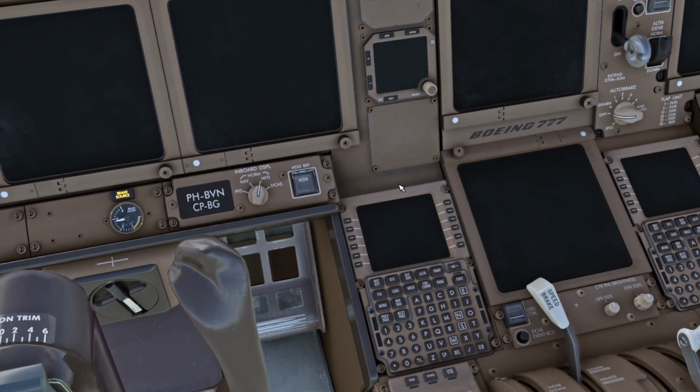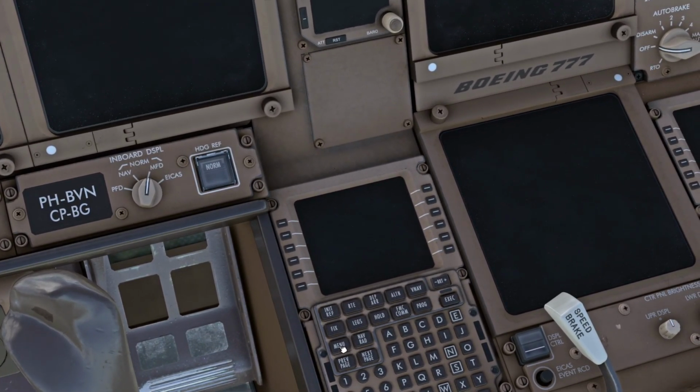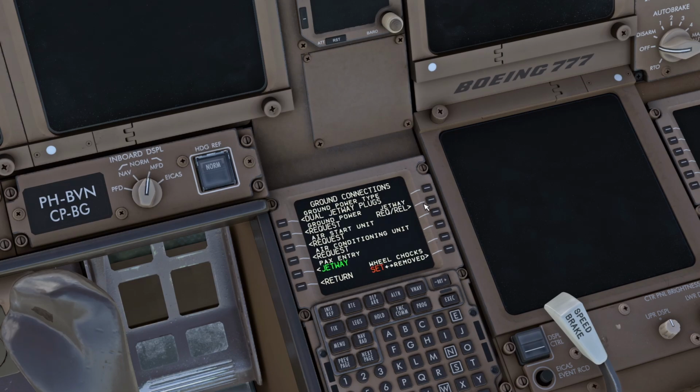For this we need to hook up some electrical power on the airplane. We do this in the PMDG 777 by holding the menu button in this cold and dark state. It will make the CDU come alive so we can access the FS Actions menu. I'm going to click on ground connections, and then we're going to request ground power.